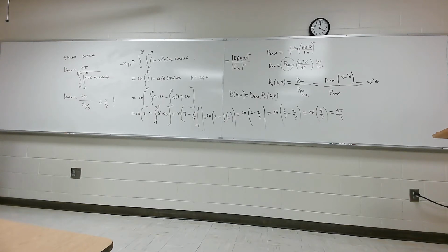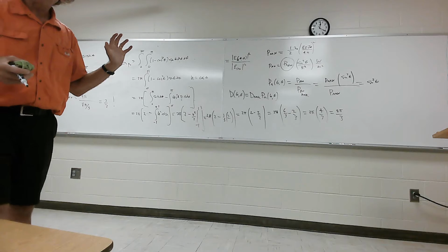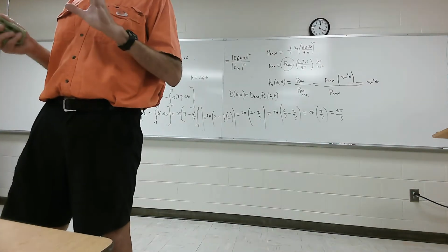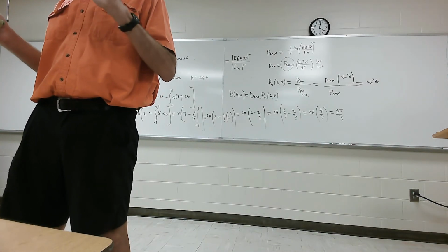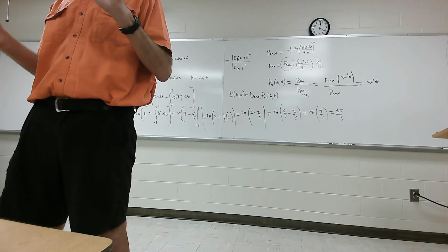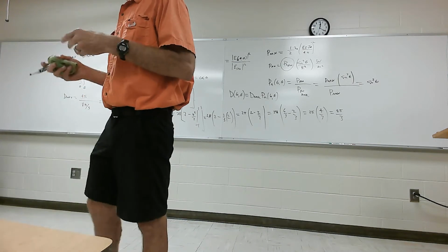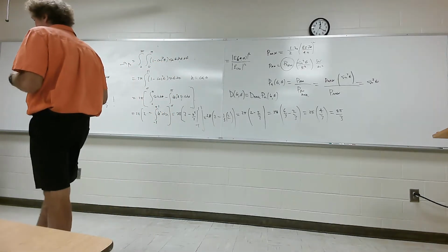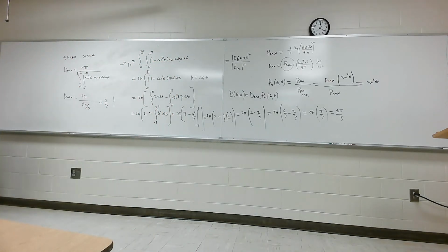Give you an idea of what directivities you can get with some high gain antennas or high directivity antennas. You can easily get 1,000 to 10,000. Alright, so they have much more focusing ability. It's saying you can get 10,000 times as much power density at the maximum or the focus point of the beam as you would with an isotropic radiator.